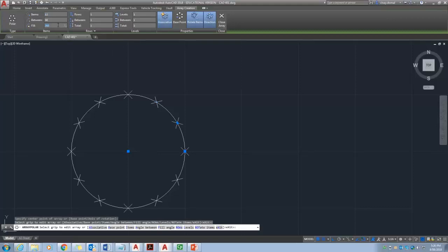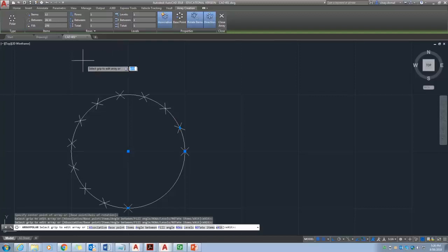So these options, in terms, if you're looking at a lesser angle, sometimes the direction will be important. If you're making 270, the direction might make a difference in which way you want to rotate, right? So that might change depending on the direction as well. But in this case it is 360 equal divisions, so direction doesn't really matter. So that's with the polar array. You really need an axis or a center point.